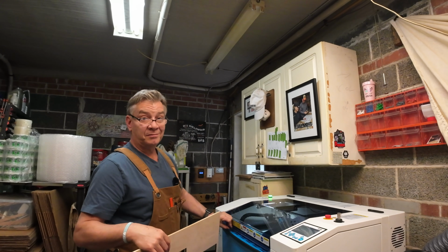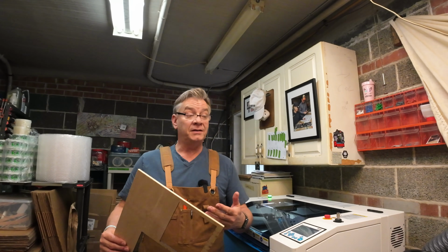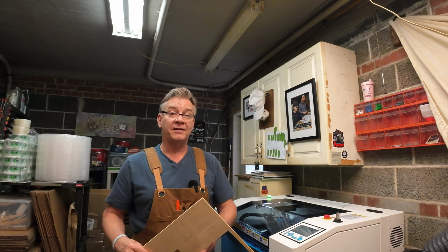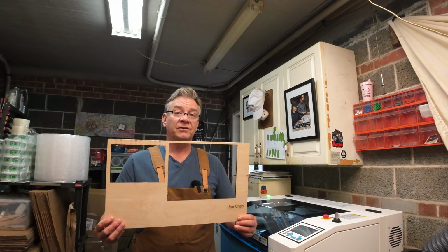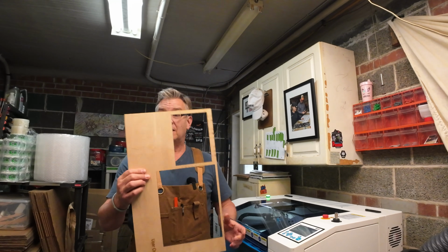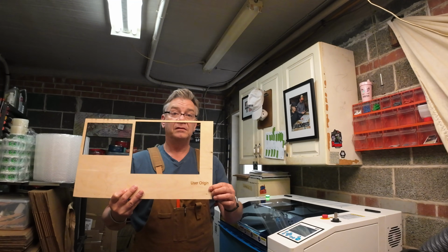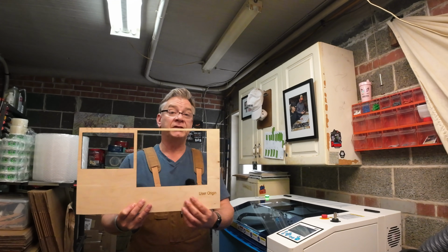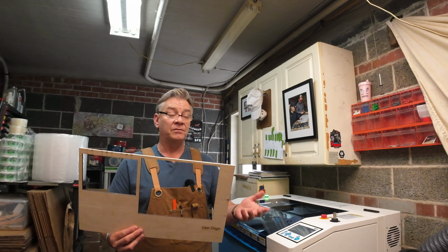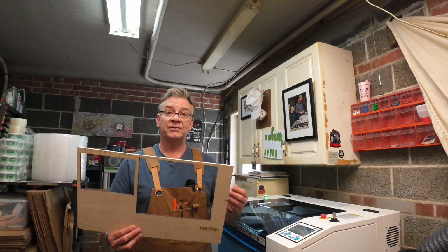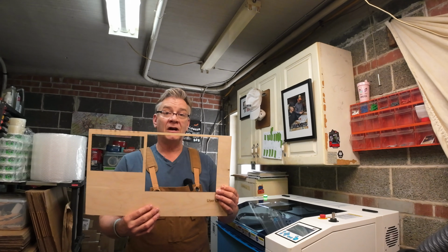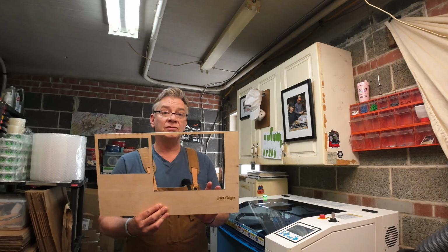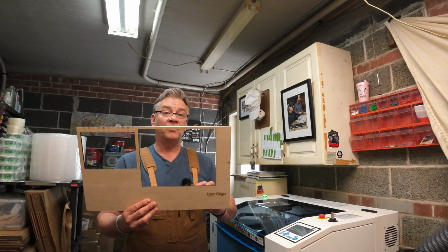Employing user origin makes a ton of sense, which is probably why it's the only thing I've used for 2.5 months. Because I'm not going to start a brand new piece of 12 by 20 inch material every time I have a job. I want to make sure that I'm using up all of the available material on each of these craft boards or coasters, tumblers, whatever it is that I'm working on. I've got lots of spare space from other jobs. I can simply utilize user origin to put my design where I want it.